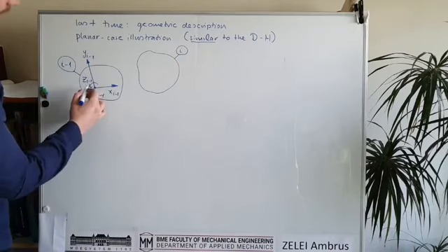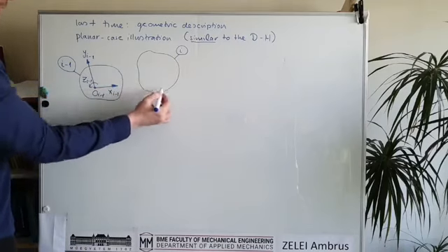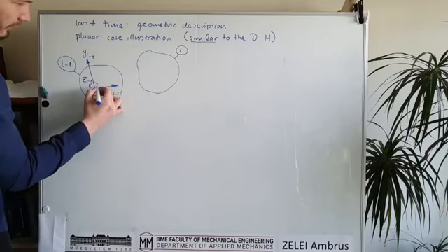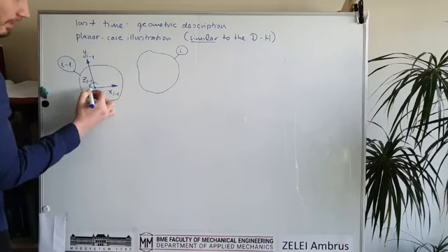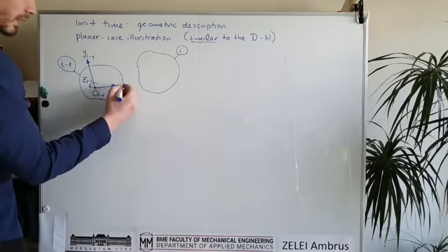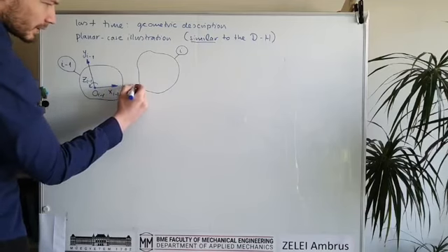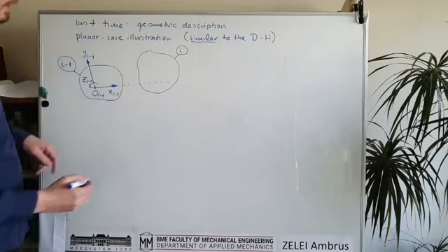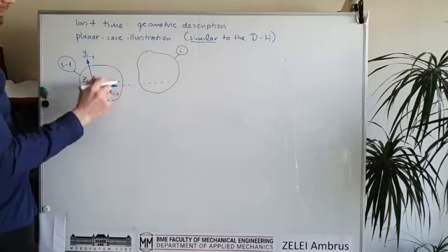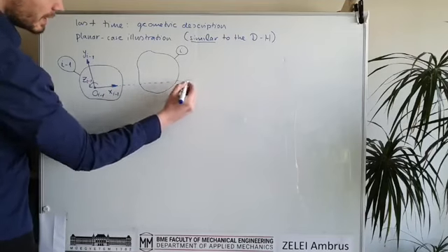And we have another coordinate system which is fixed to the other body, but the constraint is that the origin of the neighboring coordinate system must be on this line, which is the elongation of axis x of the previous link.